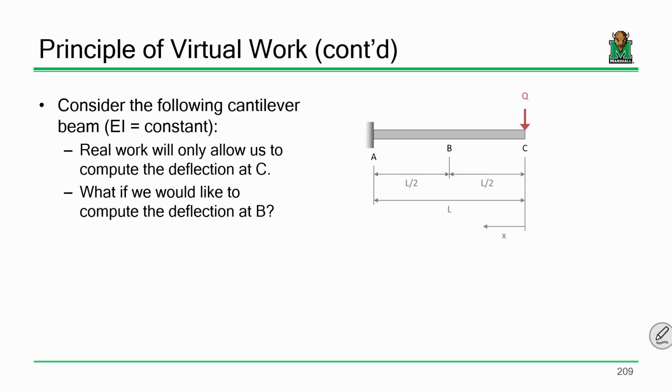Now, if you took an undergraduate course in structural analysis, you might remember the unit load method, where you take a structure, you analyze it, but then you take like a 1 kip force or a 1 kilonewton force and then apply that and do the analysis again. That's what this is, if you remember that. But we'll walk through this step by step and explain what's going on.